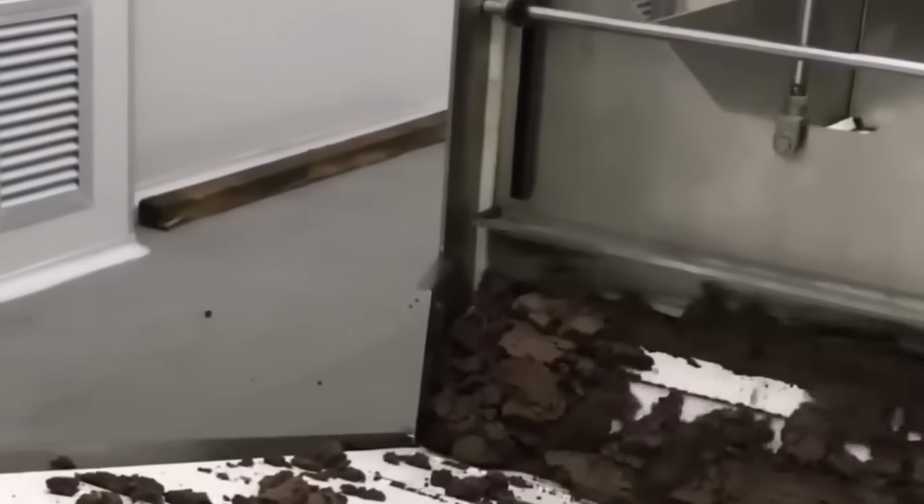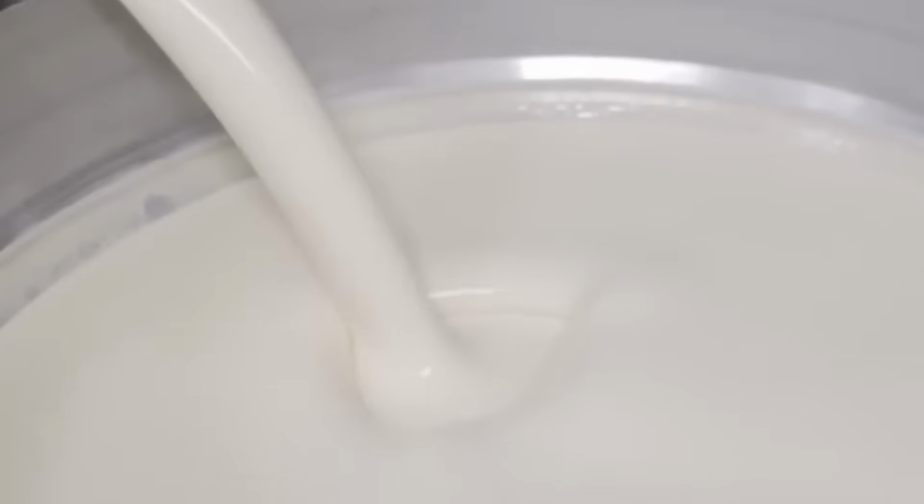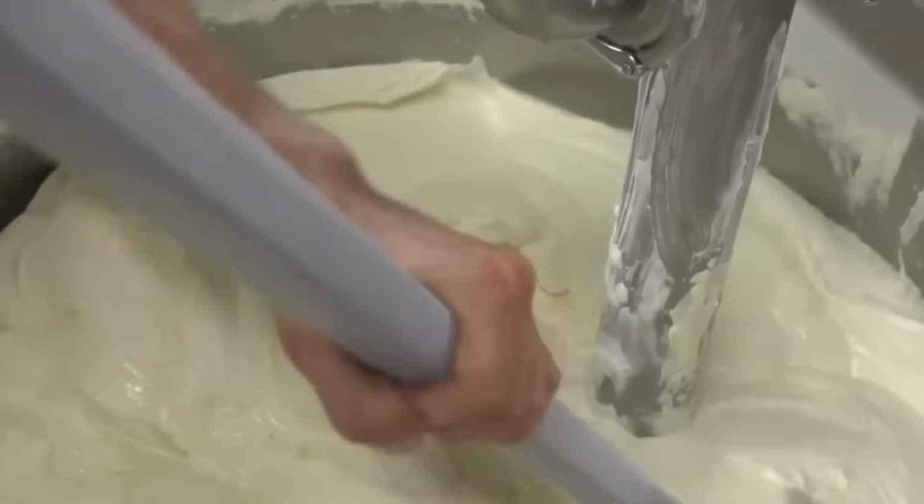Dry ingredients are metered into a high-capacity horizontal mixer with dual-axis paddles designed for uniform blending. Liquids are injected through precision nozzles mounted at the top of the mixing chamber. The total mixing cycle is programmed between 6 and 8 minutes at varying RPMs, first for dry distribution, then for incorporation of wet components.